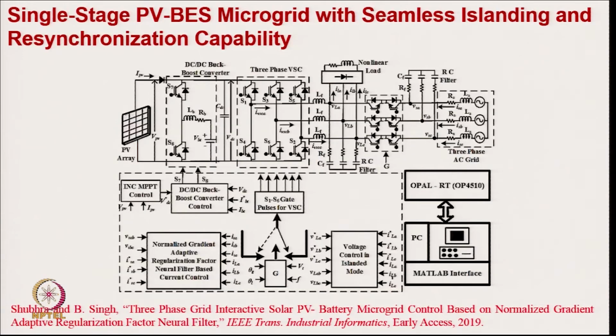With the typical system, which has a single stage PV based microgrid. So, we have a solar PV array with the single stage, and here we have the buck boost converter of the battery. This buck boost converter of the battery allows maximum power tracking by controlling the DC link voltage, so that you can eliminate one converter, and it allows the battery voltage to be at optimum voltage. Apart from that, normally under load unbalanced condition, the second harmonic in the DC link does not flow into the battery and can be curtailed.